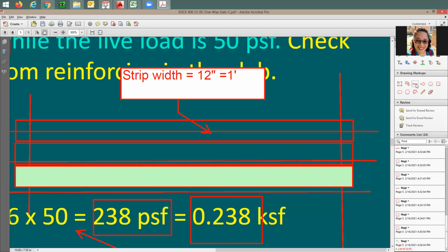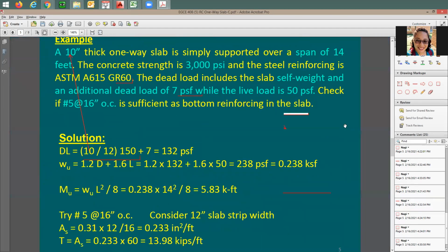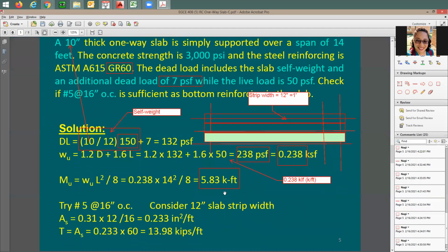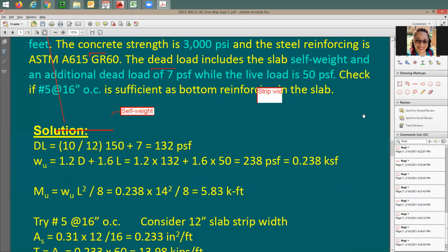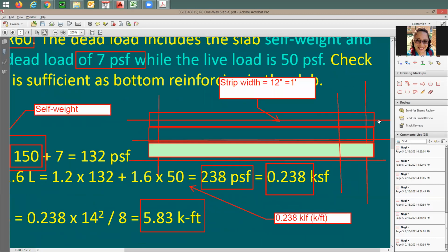So what we'd like to do is, as if you're cutting a section here, look at the bar spacing, and then look on average how much reinforcing or AS you have per 12 inches, which means per strip, on average, right? How can we do this? I'm going to say, if I have rebar at 16 inch, this rebar happens here, 16 inch, you have another rebar, 16 inch that you have a rebar. If I take the cross-section area of just one rebar divided by the spacing,